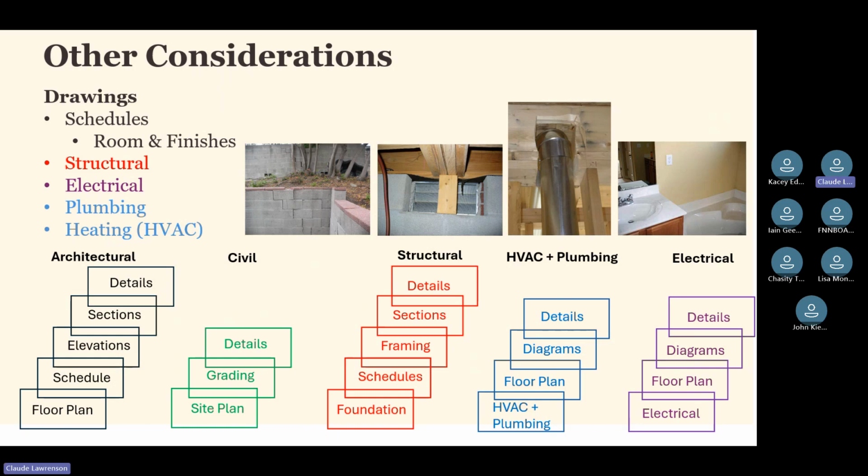Above, you'll notice I depicted 4 pictures. Retaining walls that fail, a beam on a 2x4, inadequate structural, notching of roof framing, or in this case, floor framing members.